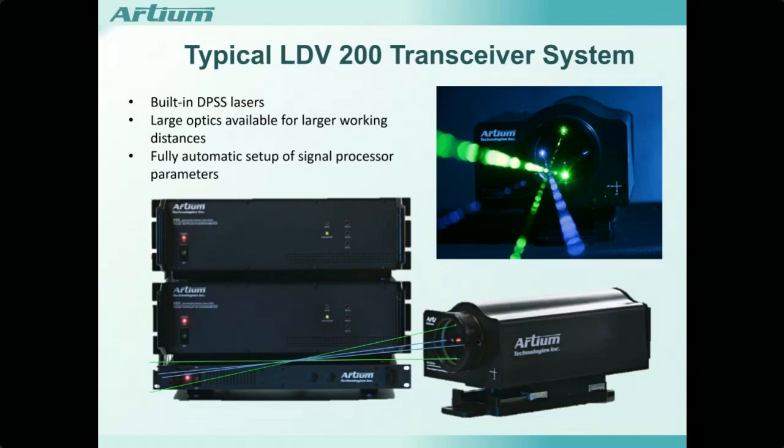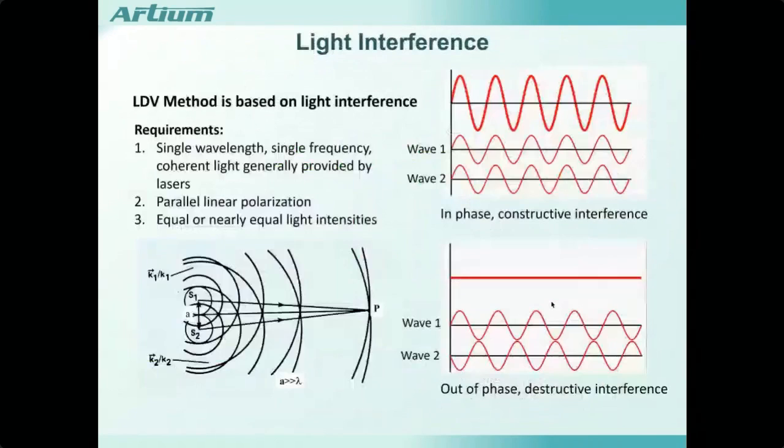So in this case, with a transceiver configuration, the beams are directed out into the flow, and then light scattered by particles at the beam intersection is detected back into the same lens and directed towards the photodetectors. So it's a convenient package, but I'll also provide some critique of that approach later on when I get into optical configurations. Whoops, sorry.